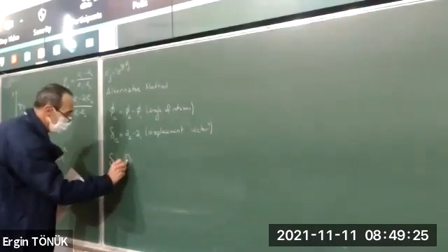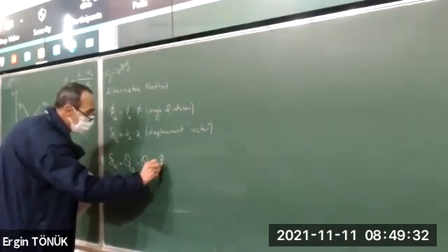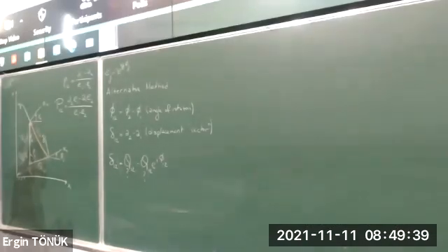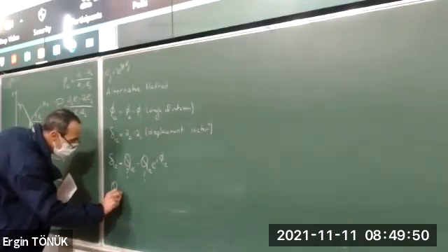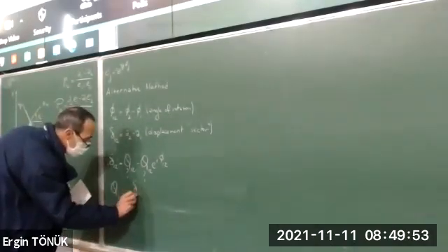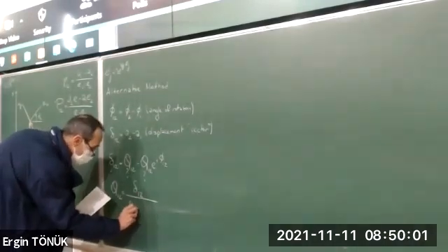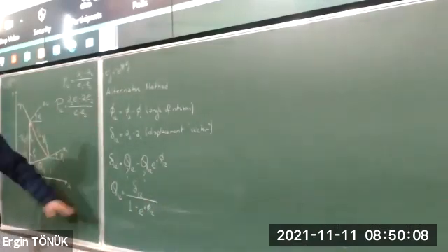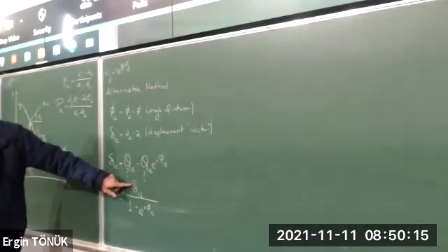So Q12 minus Q12 e to the i phi12. And this Q12 is what I'm trying to find. It's the only unknown. It's complex. The equation is complex as well, so I can solve for it. So what I obtain is Q12 is equal to the complex number representing the displacement vector over 1 minus e to the i phi12. So on the right-hand side, I know everything. Displacement is given, or I can find it from the A's or whatever.